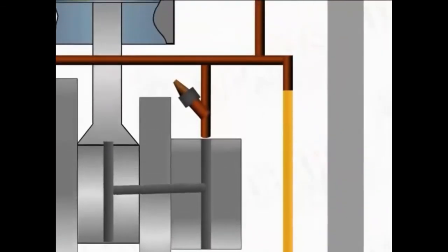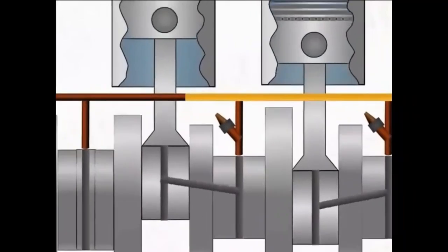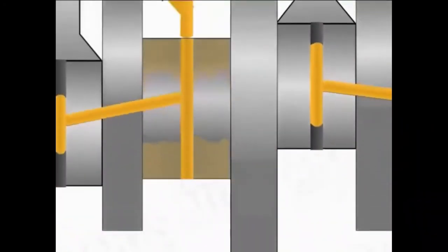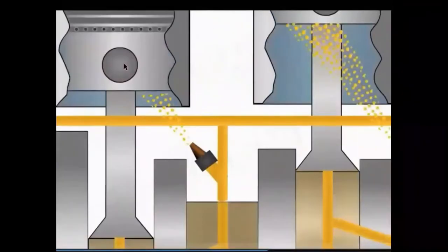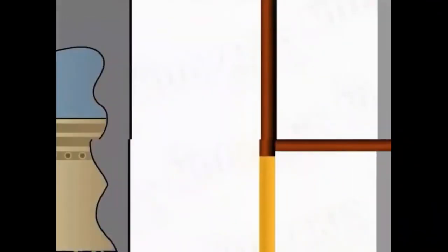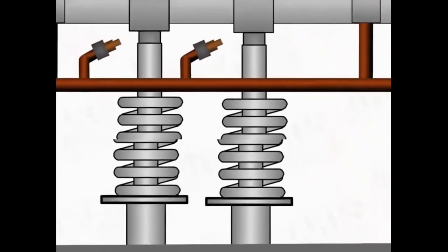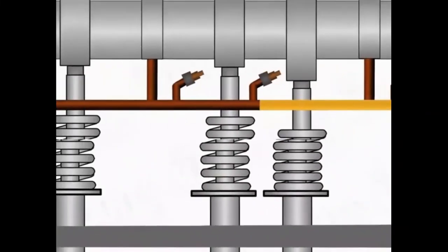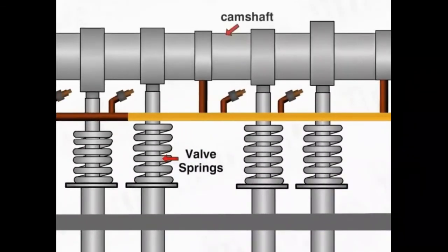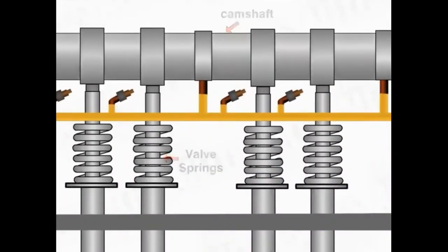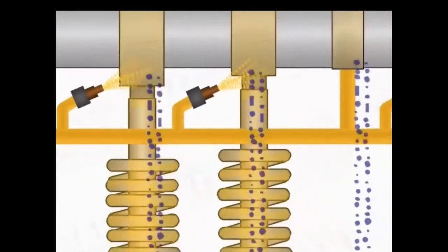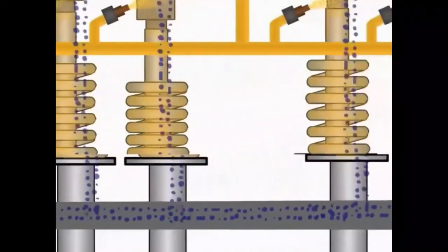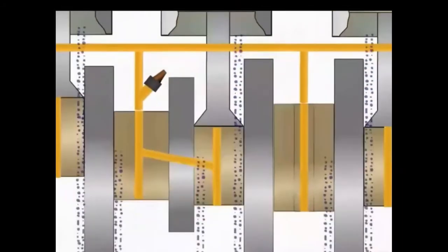Pressurized oil flows through the oil line and gallery to lubricate the moving engine parts. Now it is supplied to the different parts inside, the crankshaft and main bearing, to lubricate them. Oil also supplies the camshaft, the cam that operates the valves of the different piston cylinder mechanisms. All the oil goes down and is collected in the tray.